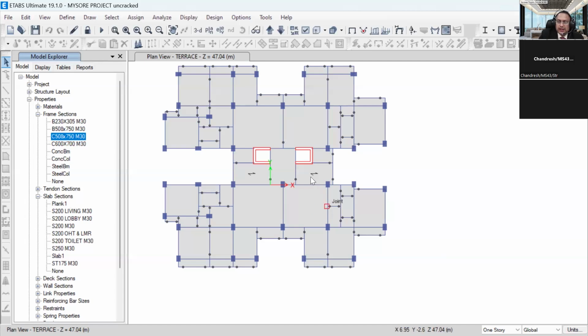Now sir, these stairs. Now see the staircase slab over here. The staircase is one way only, so this is the big span. In the staircase you might require maybe 200. This might be a little less, but at some places you have given 250 or something. Just check. I think 200 would be enough here. It was showing high deflection, sir. That's why. Almost okay. 250 are given.